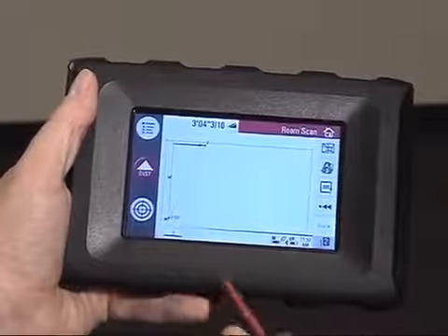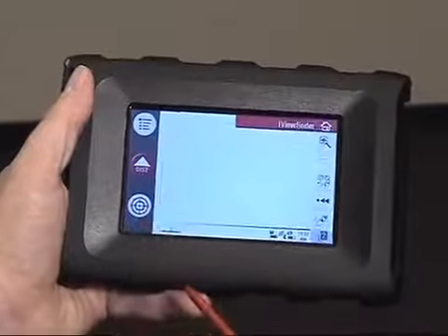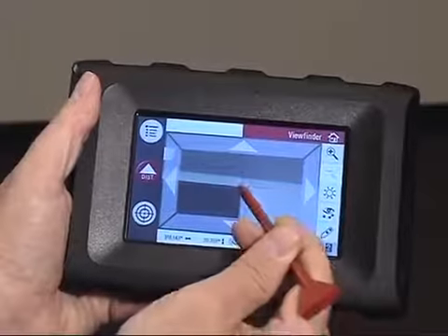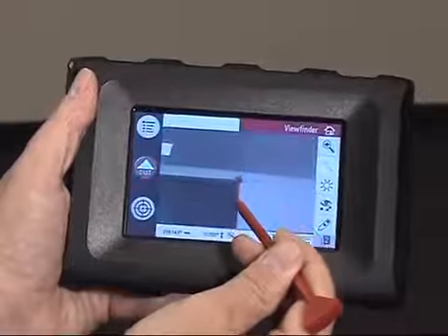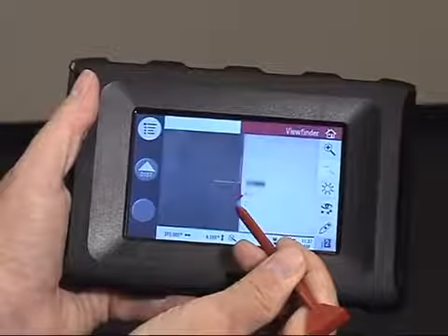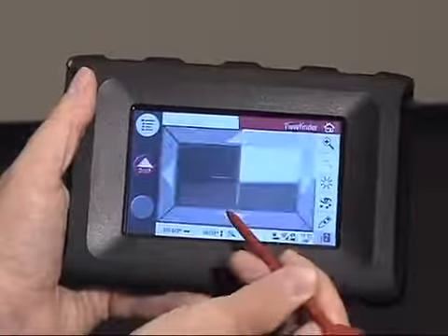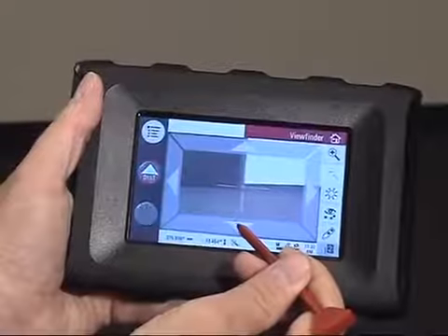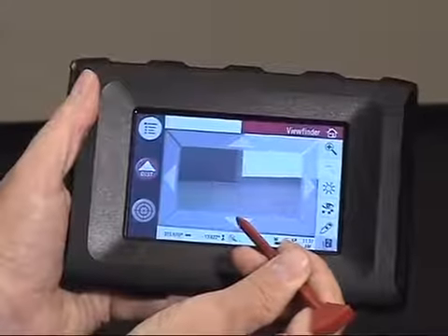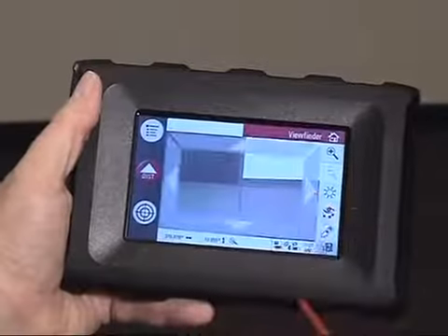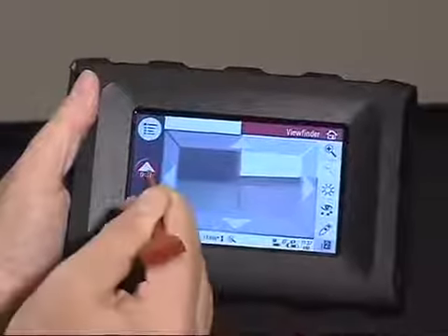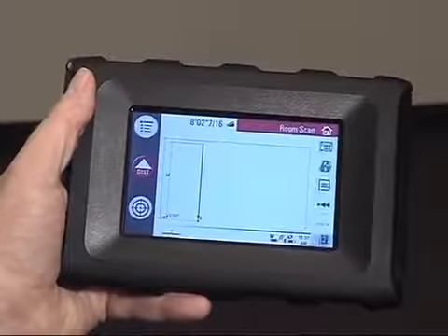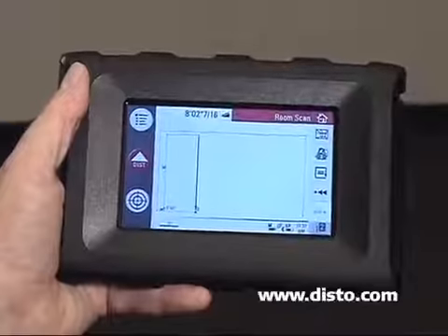Now I need to do one more at the bottom corner. Let's go ahead and hit the view screen again. Drive the unit straight down to the floor. I can visually see and look at the crosshairs on the unit. Then I need to just move down a little, move to the right, just one tap. We're down at the bottom corner of the door. Hit the dist button. Now we've located the door in that wall plane.